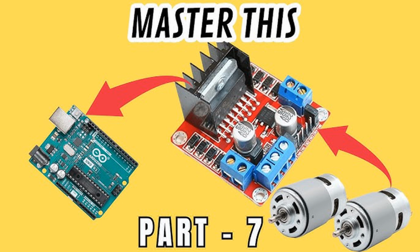Function: PWM drivers control the speed of DC motors by adjusting the average voltage supplied to the motor. Operation: By rapidly switching the motor on and off at a certain frequency, the duty cycle, PWM controls the average power. A higher duty cycle results in higher speed, while a lower duty cycle reduces speed.